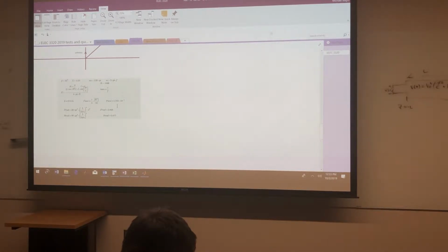One other thing, I don't remember many people doing this for this problem, but you did it for the next one. They also knew that the gain of that antenna was 1.5, the directivity or gain. So if I know that, then I know the power density, P average, would be the power radiated. Let me put this down right here so you can appreciate what I'm saying.